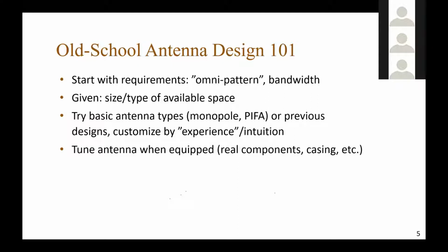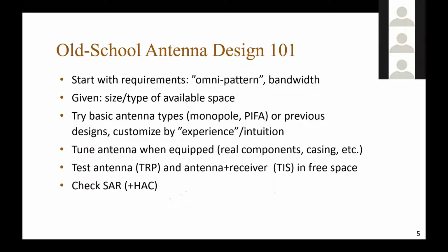And of course, we then go on to put in some basic antenna types. Usually, it's kind of monopole, PIFA, some variants of these. Or you try to use a previous design and customize it by experience and intuition. Then you put in the components and see what they do to your antennas, and you tune the antennas back to the required bands. You test the antennas to make sure that they radiate properly, they receive properly, and you check that they are safe with respect to SAR exposure.